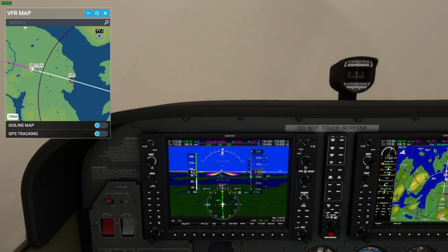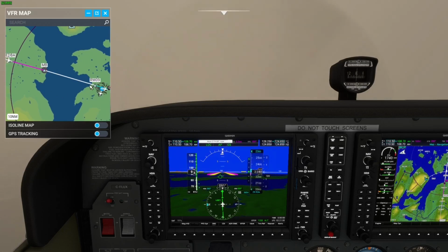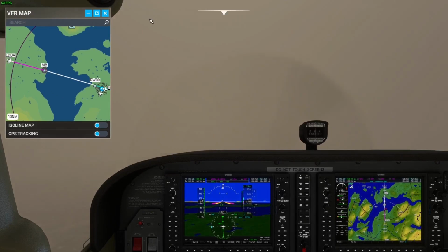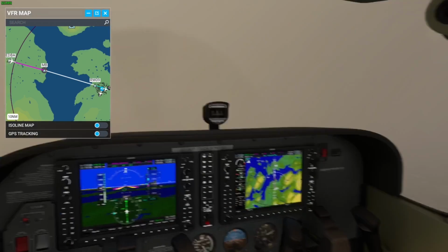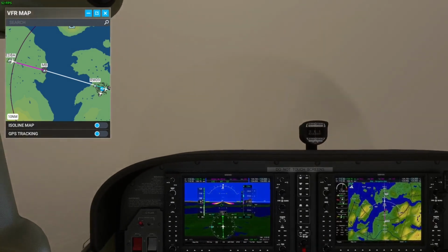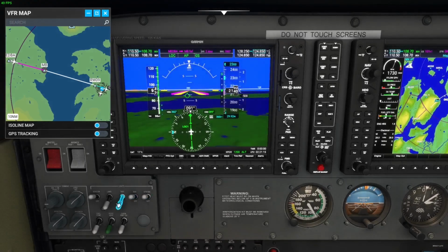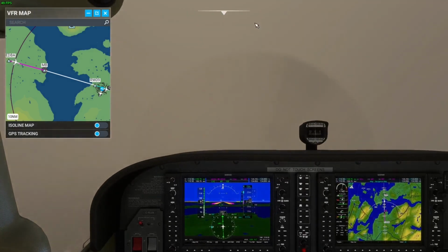So now what's improved is that the plane will automatically take care of altitude. So it'll fly left and right centered and up and down centered. All we now have to do with the throttle is make the plane speed up and slow down. So you see how things have changed. Now the throttle changes the speed of the aircraft. And the ILS, automated system, will make sure the plane follows at the exact correct descent rate.